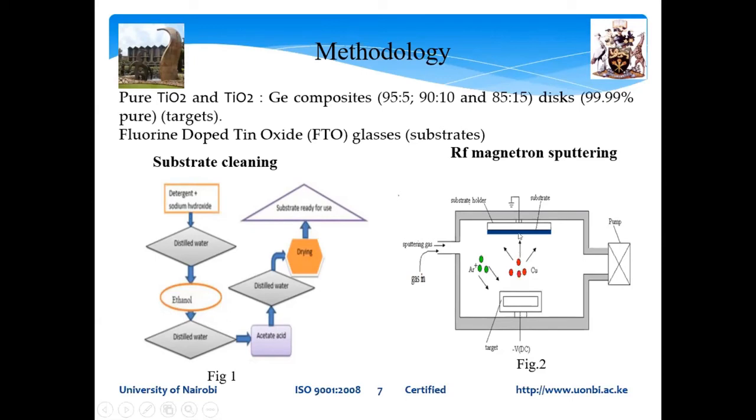And then these materials travel in this vacuum and condense on the surface of this substrate to form a film. It is a good method because we expect no or minimal contamination of the film because the whole process is carried out in the vacuum.